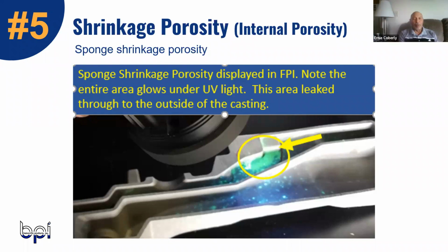Actually, it really depends on the casting section you're attaching it to. If you've got a half-inch wall and you're going to put a 4-inch riser on top of it, it does absolutely no good at all, because as soon as the wall stops feeding, the riser stops feeding. You've got to remember everything in the riser has to feed through the part. So you've got to look at what it's attached to. As soon as the casting solidifies, the riser is done.